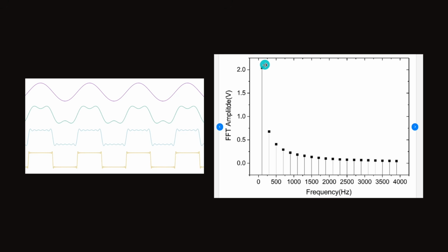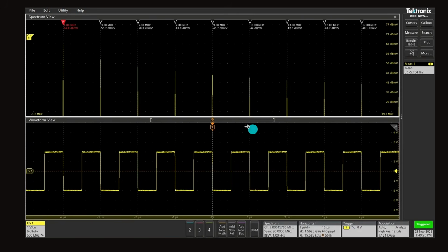Here is a theoretical model of how it happens. Yeah, you're clipping here. From a sine wave you become kind of a square wave. You generate all those harmonics going into the tweeter region, and the tweeter is dead. And here is just one screenshot from one manufacturer where they measured square wave harmonics just to show that theory and practice match. Tektronix is a good measurement device manufacturer, making really advanced devices, and it's measured. Yeah, this is measured at 1 megahertz, but the spectrum is the same. And for audio, we have the same principle.